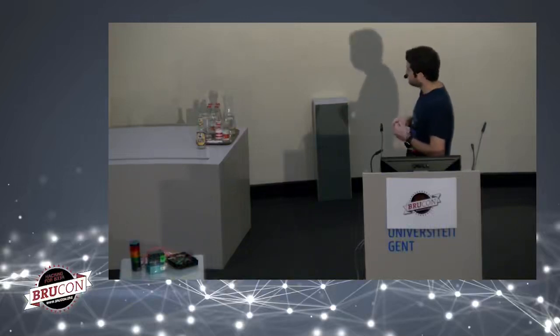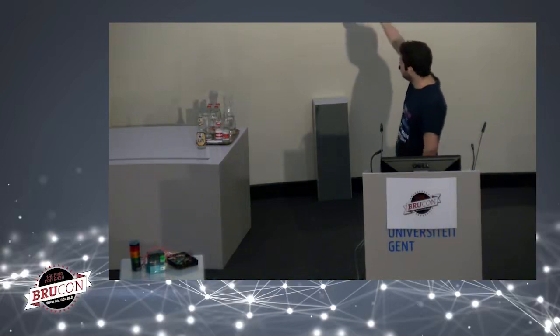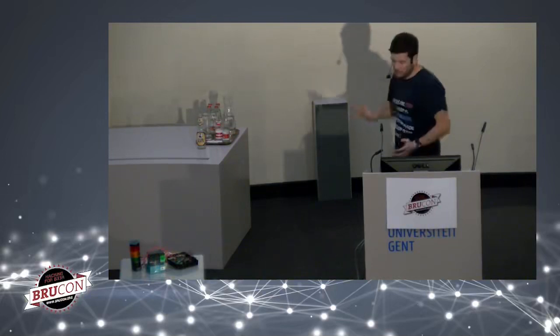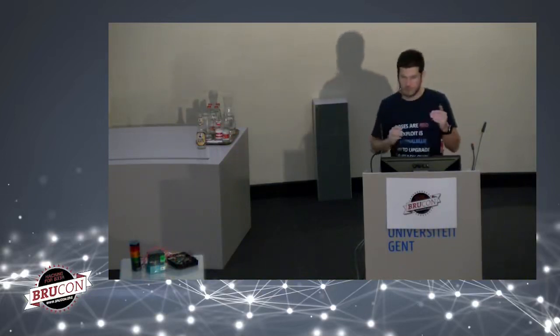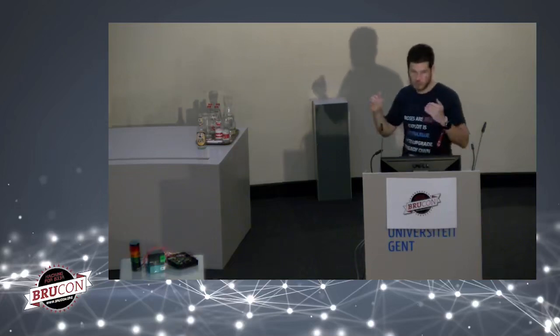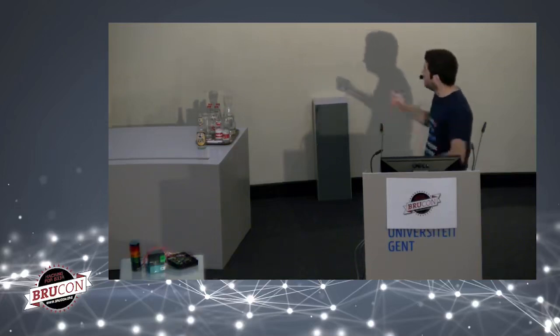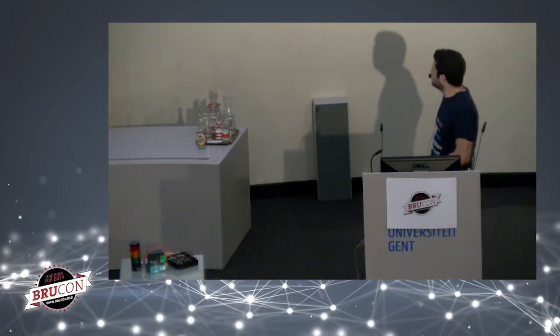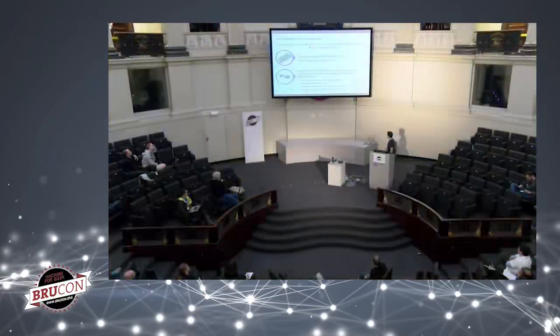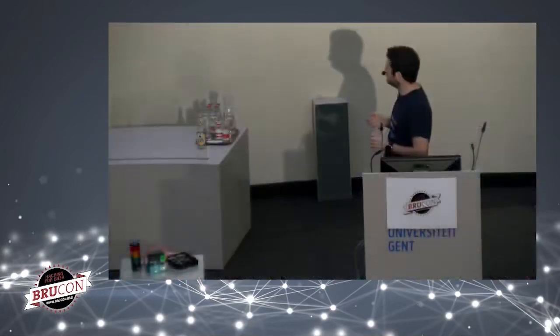What is an optocoupler? As you can see here in the diagram, basically it's a light emitting diode on one side, it's a photodiode on the other side, and so it allows you to transmit information through this tiny integrated circuit. It's quite cheap because, let's say the chip is about €2. It has an acceptable bandwidth.